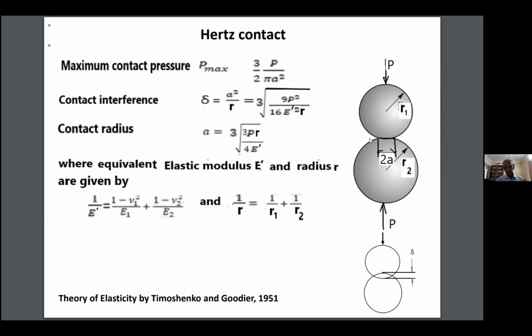The 2 points are approaching together. If you deform, say, 2 rubber balls, points away from the contact are deforming as well as approaching. Using this very elegantly, Hertz has shown that this type of expressions come. The derivation is very simple, but it has a fundamental elastic understanding.